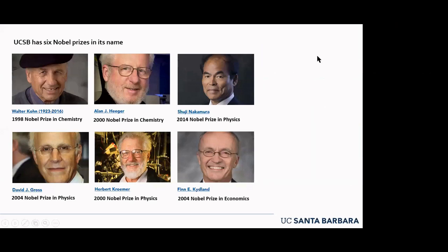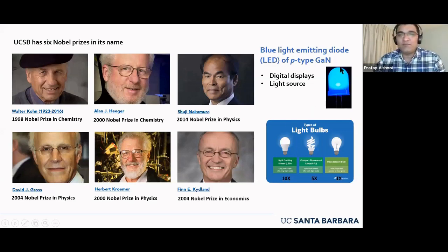Now a question arises here: how can we make a white light LED out of this blue LED? So the simple answer is we can take two other LEDs, which are green and red. Mixed with this, we have 3 LEDs, and that is nothing but RGB, and it will give white light that can be used for lighting houses. The other technique which can be used is to coat this LED with another material called phosphor.